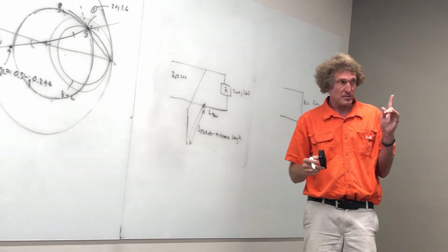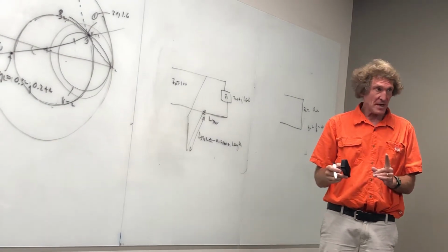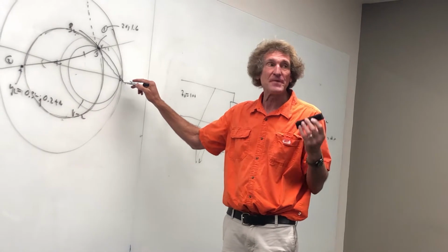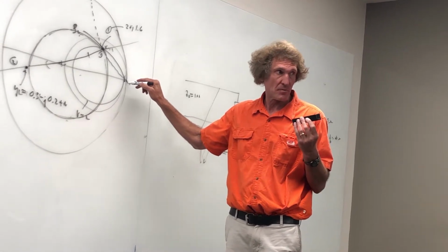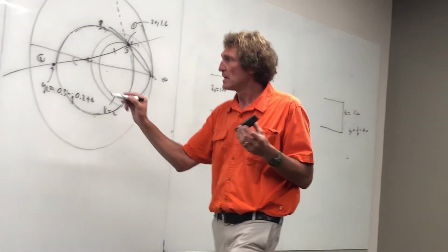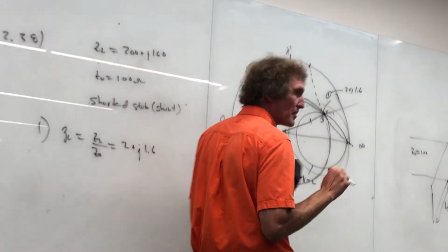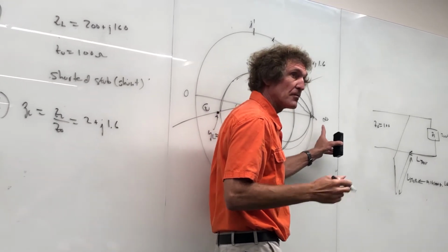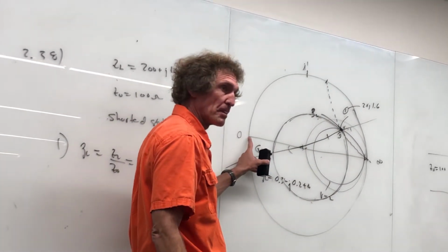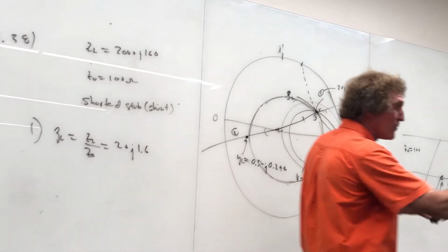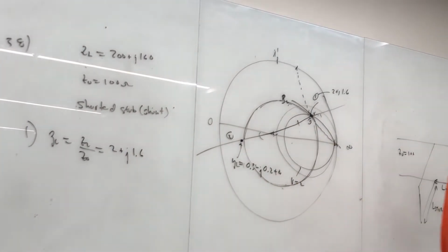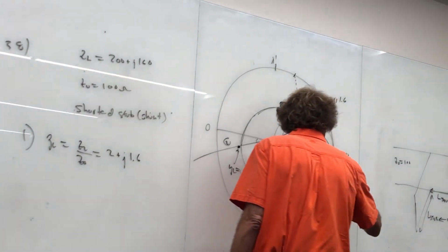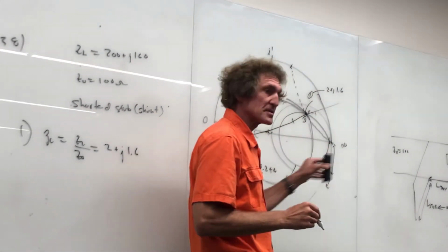Now, this is important. When we do impedance matching for the stub, we start at a point where it is infinity. This is the point. This would be infinity, this would be 0. I think we all know that, right? You would start here if it's short. If it was open circuit, you would start here. Remember, I'm moving towards the generator, so I'm moving this way, or I'm really going in this direction as I get further from that stub, right?